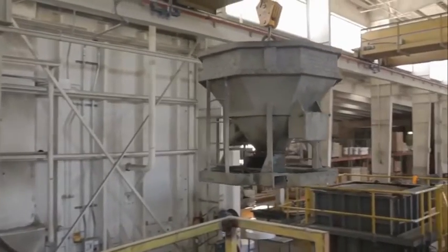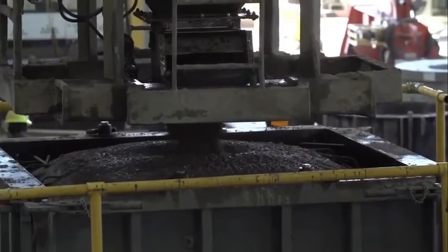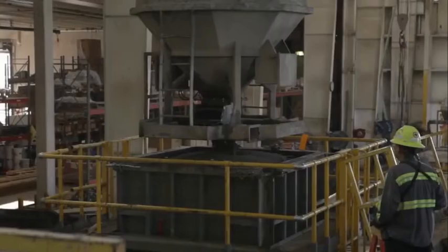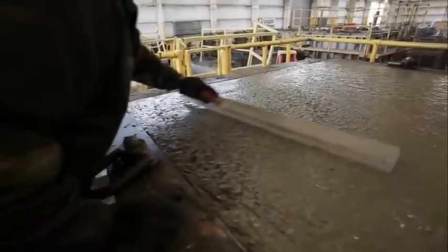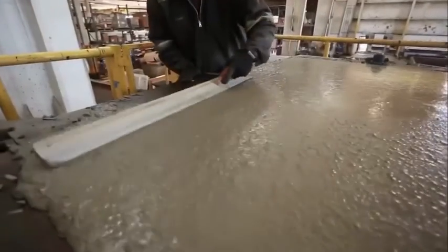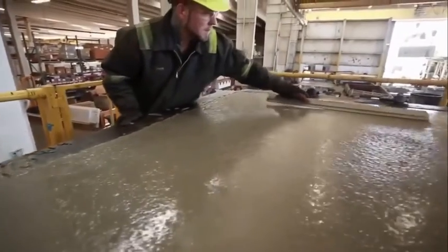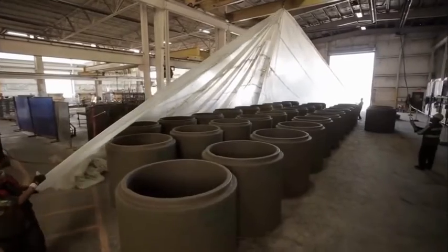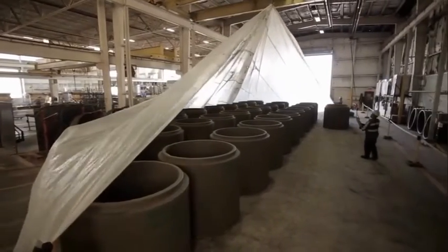Concrete is placed into the form from on location, and care is taken to allow the concrete to float without entrapping air voids. Once the form is filled, the top of the form is screeded off and the specified finish is applied. Once the concrete is placed, the curing process begins. This may include tarping the product overnight in order to capture the heat from the hydration process.